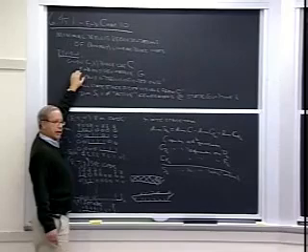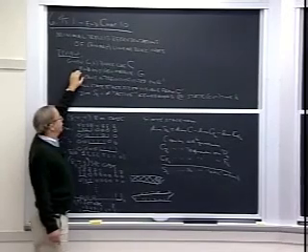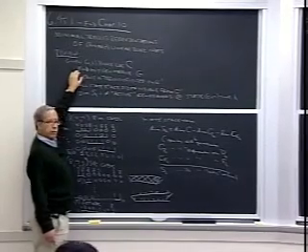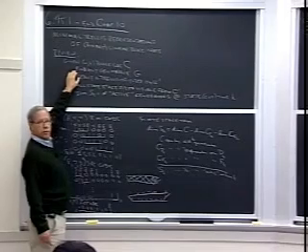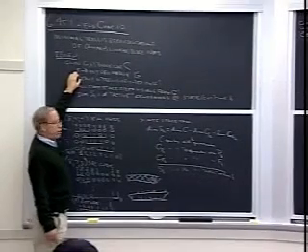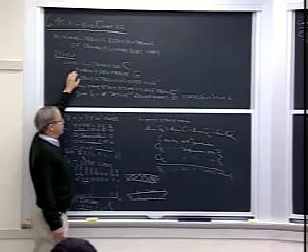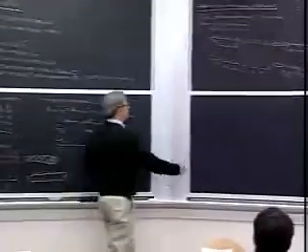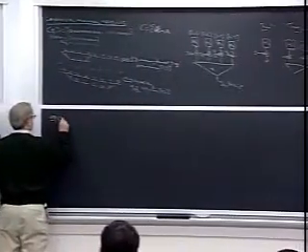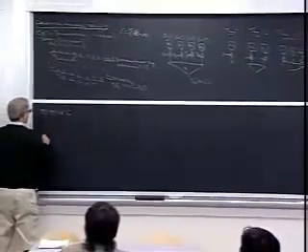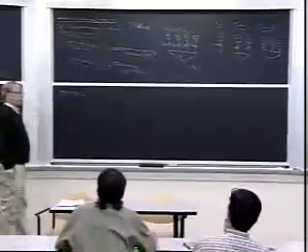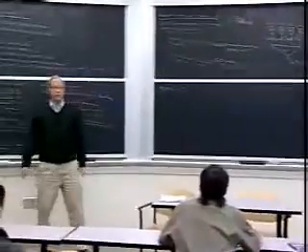Basically, we take any code word in the code, and all of its shifts will generate the code. Any non-zero code word, all of its time shifts generate the convolutional code. But we then take any code word g(D) in a convolutional code, and g(D), D g(D), D squared g(D), and so forth generate the code.